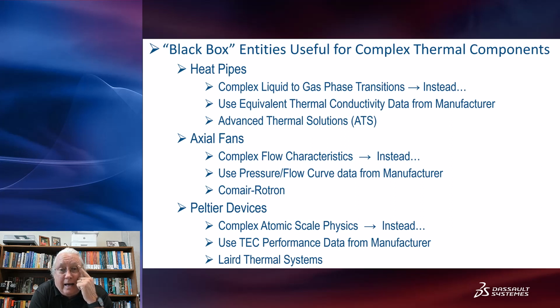The last entity I used was these thermoelectric coolers, and that's like the other two. They're a very complex mechanism for heat transfer. It's at the atomic scale. There's a bunch of physics involved. So instead of dealing with that, we just use the TEC performance data from the manufacturer. We can input that into SolidWorks as parameters, and we get those from Laird Thermal Systems, who manufactures the Peltier devices. So those are the three different black box entities that we used in SolidWorks simulation. So let's go through those one at a time.